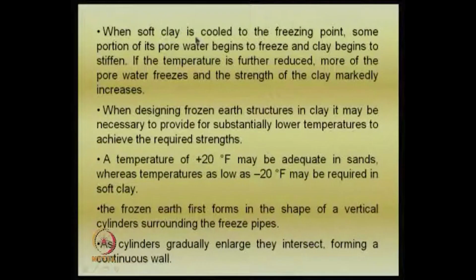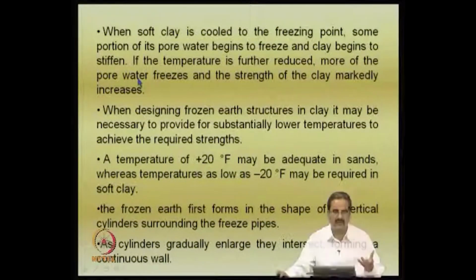When a soft clay is cooled to the freezing point, some portion of its pore water begins to freeze and the clay begins to stiffen. Why it works is that soft soil has a lot of water content, and the pore water freezes and the clay begins to stiffen. If the temperature is further reduced, more of the pore water freezes and the strength of the clay markedly increases. This is actually the mechanism, and when designing frozen earth structures, it may be necessary to provide substantially lower temperatures to achieve the required strength.